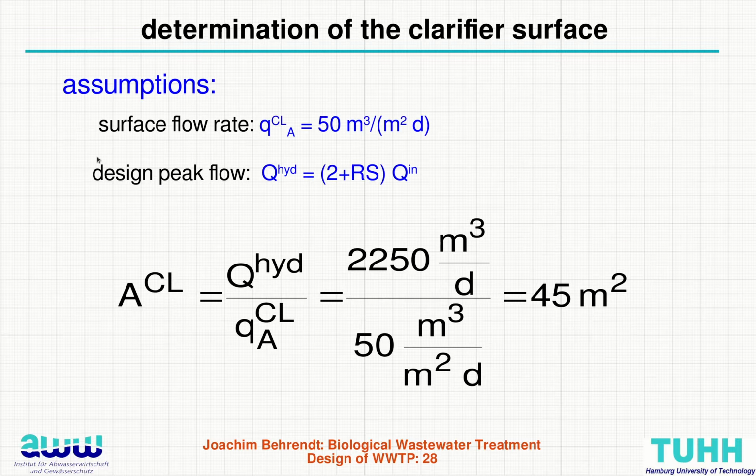And for the clarifier, we know that we have a maximum surface flow rate of 50 cubic meters per square meter and day. This is in the range of 2 meters per hour.